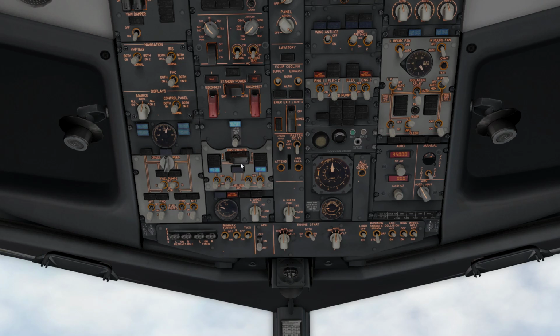So earlier we had turned on in the second row our ground power, and just below it, and above this exhaust gas, in the center is the APU gen switches. We have two of them. When the APU is fully up to its speed, it will be ready to generate electricity as well as bleed air. So we're waiting for that blue light, and then we can transfer over.